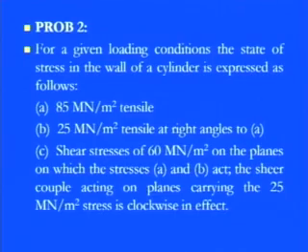In a clockwise direction, meaning wherever I am considering the 25 mega Newton per meter square, on the top side I have the shear stress. The shear stress is occurring on the plane where the vertical 25 mega Newton per meter square stress is acting. So both are acting on the same plane, one is normal, one is parallel. This shear stress component always combines with the 25 mega Newton per meter square, and its direction is always clockwise.